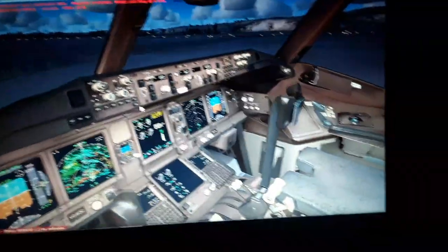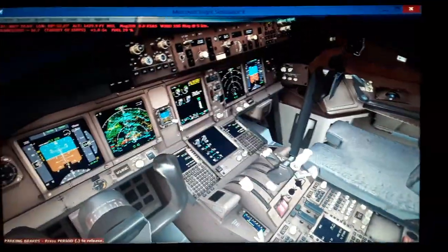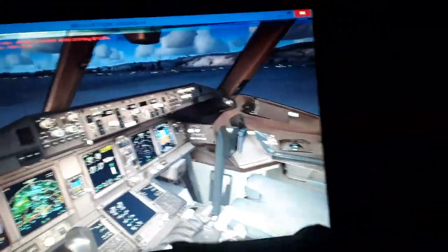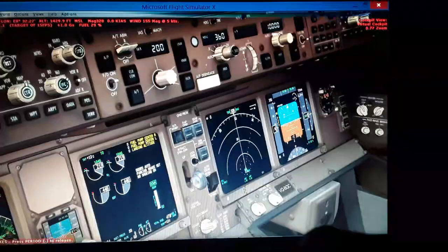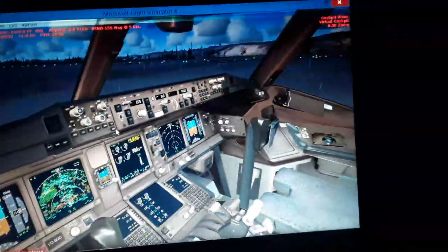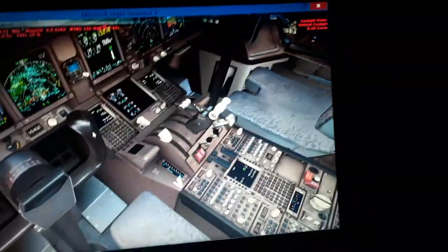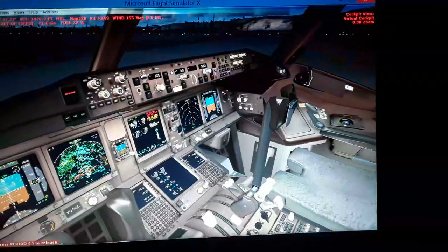Also, if we engage the autopilot, the thrust command, the airspeed over here, and the autopilot and the auto throttle move the thrust levers to a position. This gives a signal to the FADEC to command the engine thrust required for an airspeed or flight attitude of the aircraft. So I'm going to show you also how to do that.